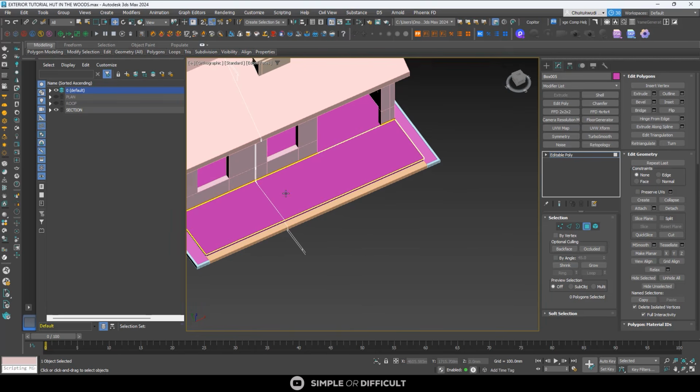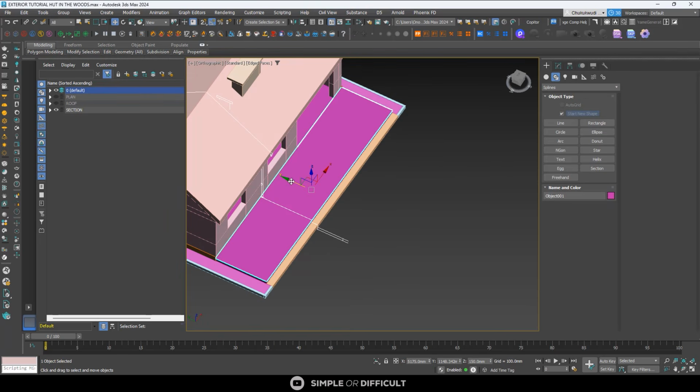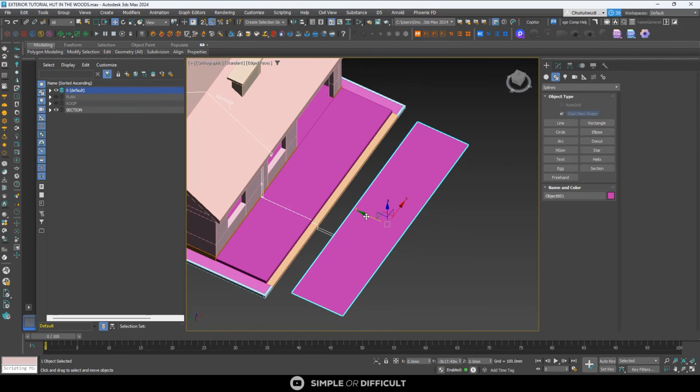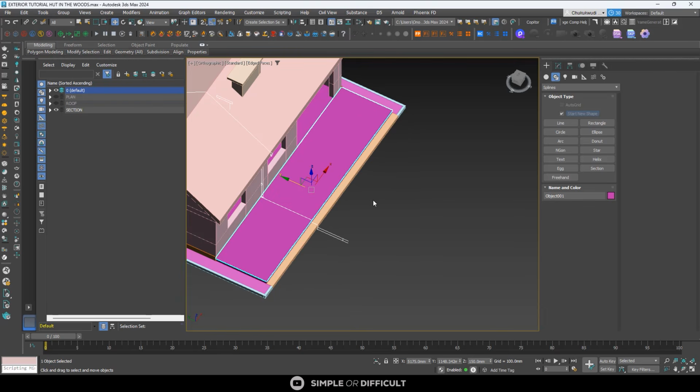What that does is when you do the detaching, it will copy that part out for you, so it is not going to create an opening for you. If you don't detach as a clone, it's going to tear it out while leaving an opening from where I just took it from.